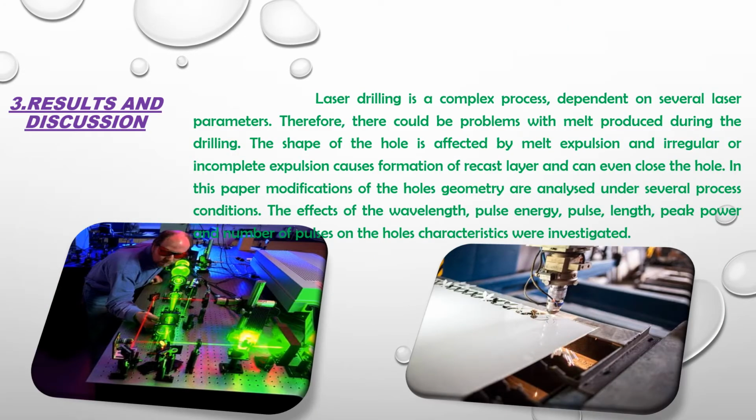Results and discussion. Laser drilling is a complex process dependent on several laser parameters. Therefore, there could be problems with melt produced during the drilling. The shape of the hole is affected by melt expulsion, and irregular incomplete expulsion causes formation of a recast layer and can even close the hole. In this paper, modifications of hole geometries are analyzed under several process conditions. The effect of the wavelength, pulse energy, pulse length, pulse power, and number of pulses on the hole's characteristics were investigated.